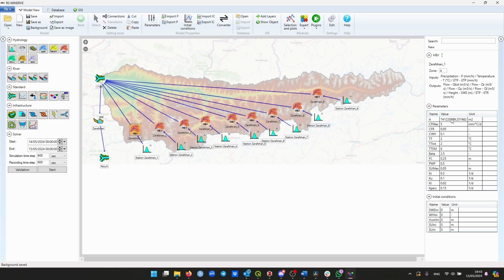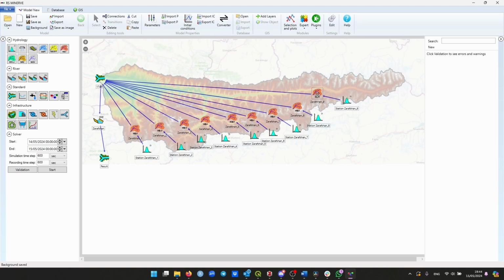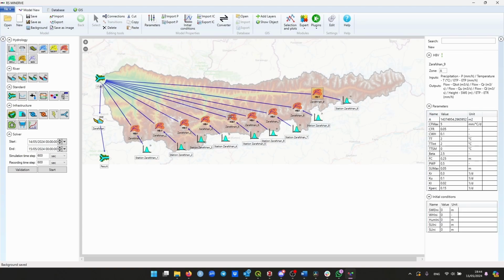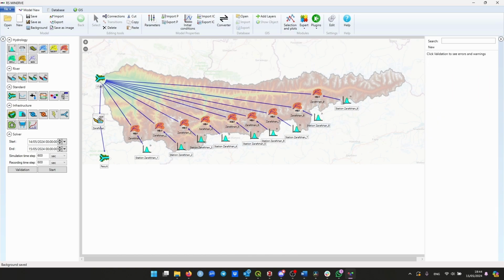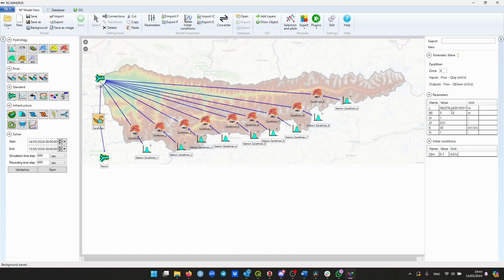And you need to check this surface area and length values because sometimes computers make mistakes and you need to double check these surface area values for each elevation band. These kinds of mistakes do happen, so be careful and double check.